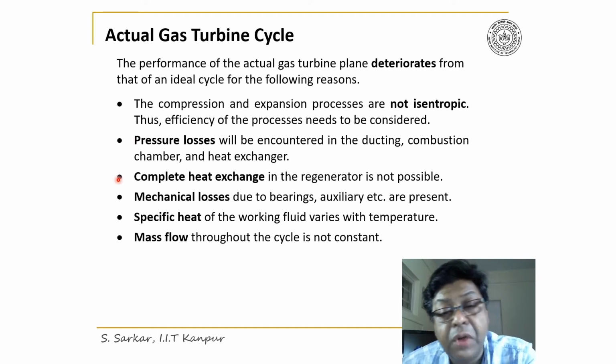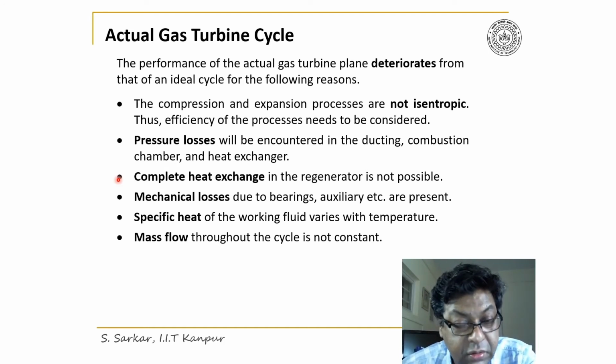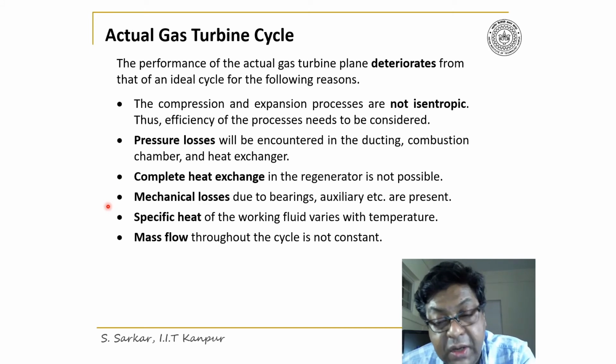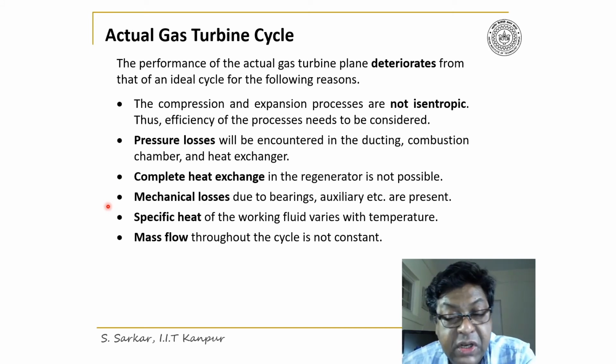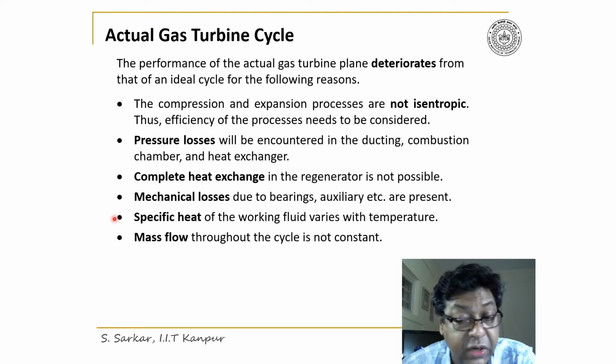Next, complete heat exchange in the regenerator is not possible. Furthermore, the mechanical efficiency due to bearings and auxiliaries must be considered. So there will be some losses. Then the specific heat of the working fluid varies with the temperature. They are not constant.